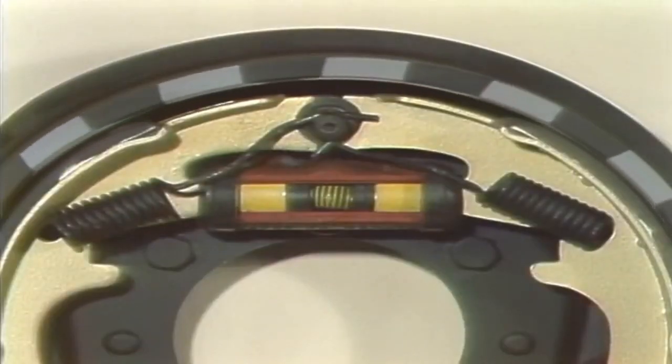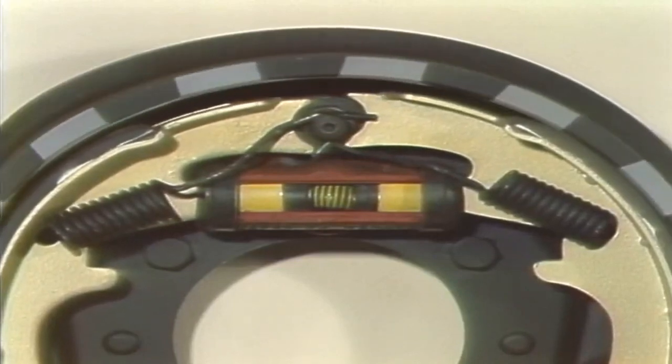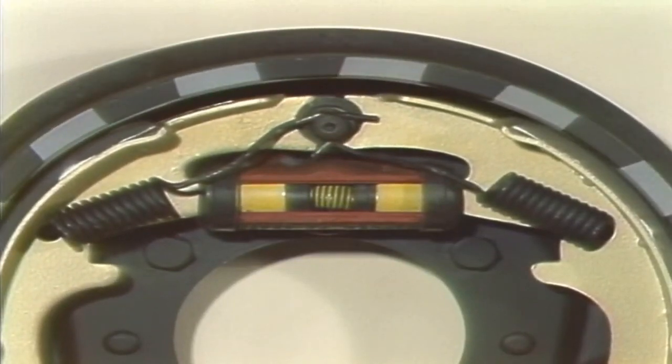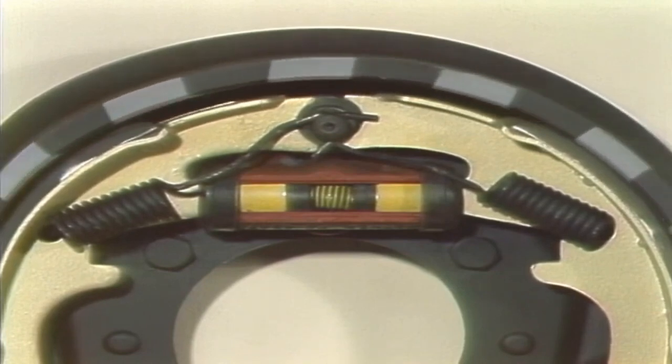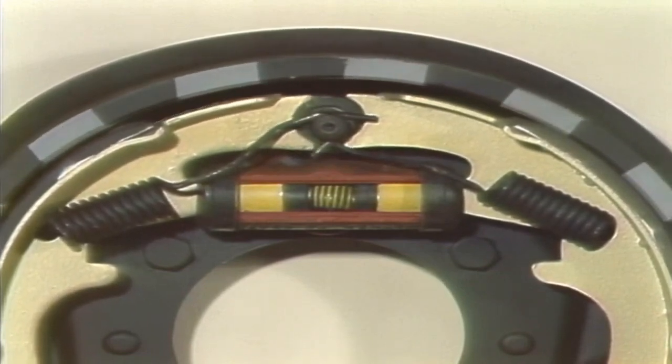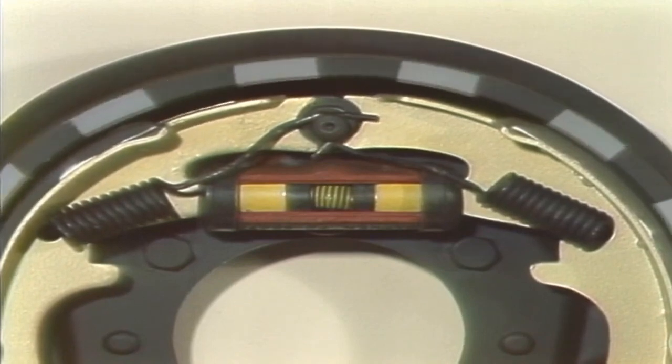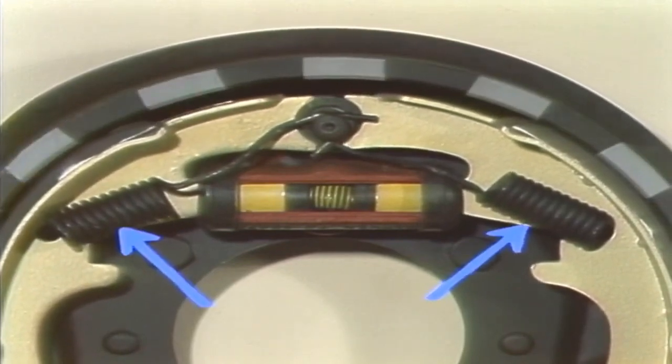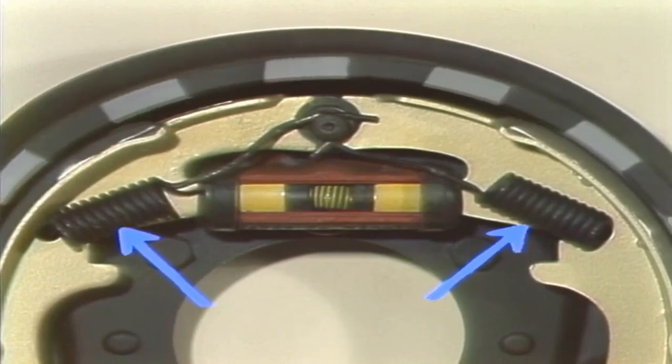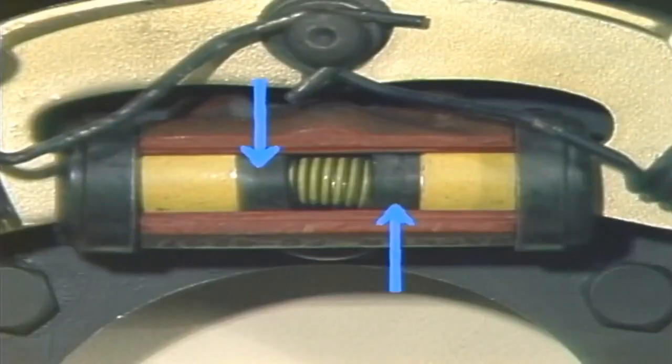The combined area of wheel cylinder pistons is larger than that of the master cylinder piston. So the force that the master cylinder piston applies is multiplied several times, adding to the force provided by brake pedal leverage. As the piston in the master cylinder puts pressure on the brake fluid, this forces the wheel cylinder pistons to move the brake shoes apart. We've exaggerated the action here, so you can see what happens. Brake shoe springs return the pistons to their stops as brake pedal pressure is released. The piston cups face inward, and so prevent brake fluid from leaking out.